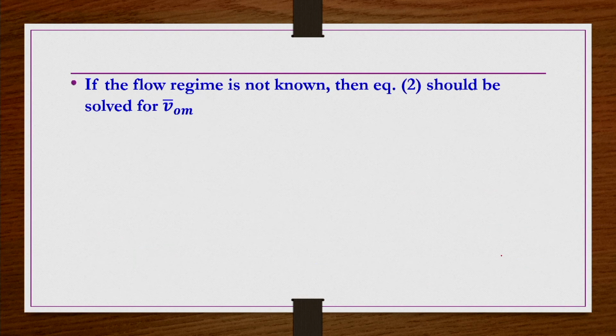So, these previous two expressions for low Reynolds number and high Reynolds number we have seen. If you do not know the flow regime, you should know Re_p, that is dp rho V0m bar by mu (1 minus epsilon_m). So you should know the velocity, then only you know the Reynolds number, and then only you can use those minimum fluidization velocity expressions. Indeed, those simplifications were done in order to get the minimum fluidization velocity.